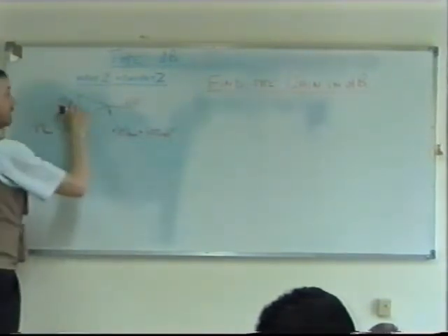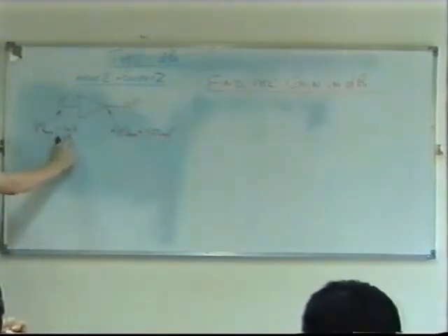This one is actually probably easier than that. If you just think about the input power and output power, make up a value if you want, 1 kilo or whatever, it doesn't matter because it cancels. But first of all, if I said I've got an input voltage of 1 millivolt, for example, how would you find the input power by means of a formula? Power is equal to I times V. If we don't know I, but we do know V and R, power is equal to V squared over R.